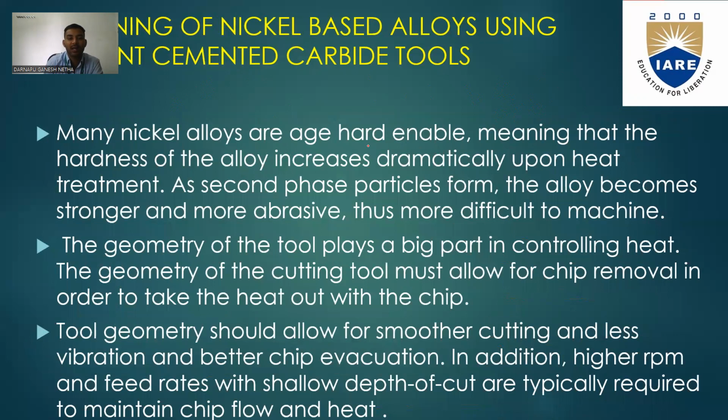Many nickel alloys are age hardened, which makes machining difficult, as the hardness of the alloys increases dramatically upon heat treatment. As second phase particles form, the alloys become stronger and more abrasive, and difficult to machine.